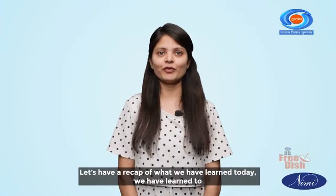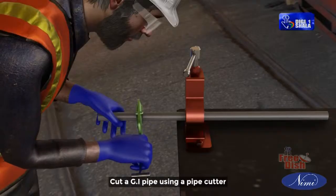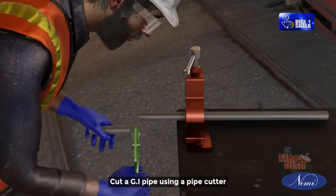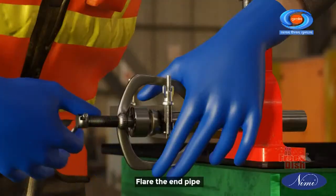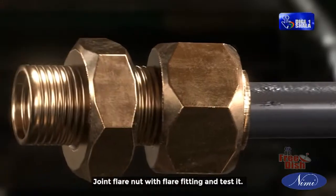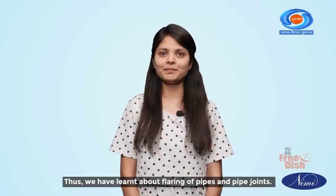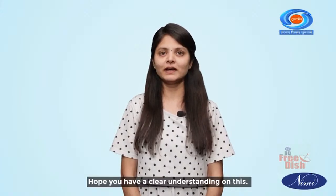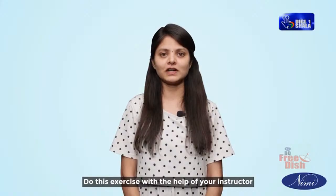Let's have a recap of what we have learned today. We have learned to cut a GI pipe using a pipe cutter, remove burrs using a pipe reamer, flare the end of the pipe, join the flare nut with the flare fitting and test it. Thus, we have learnt about flaring of pipes and pipe joints. Hope you have a clear understanding of this. Do this exercise with the help of your instructor.